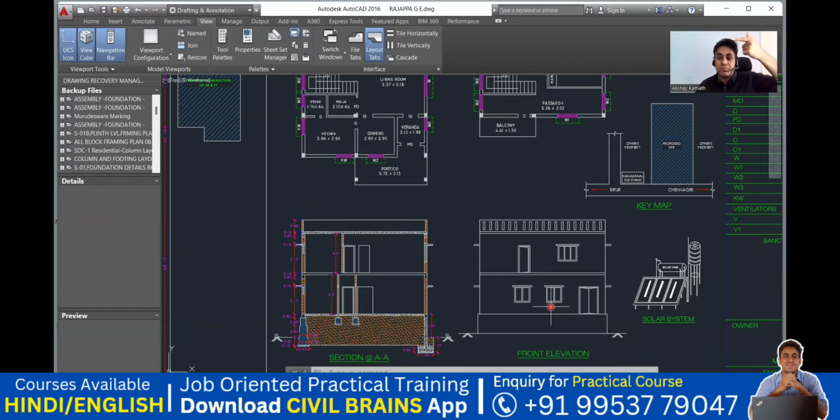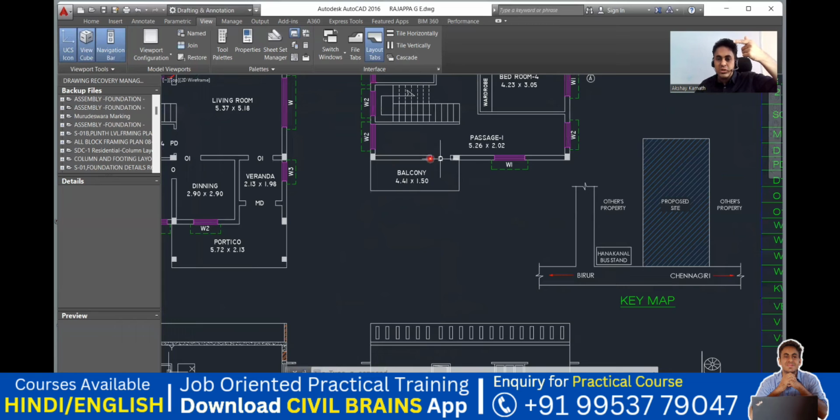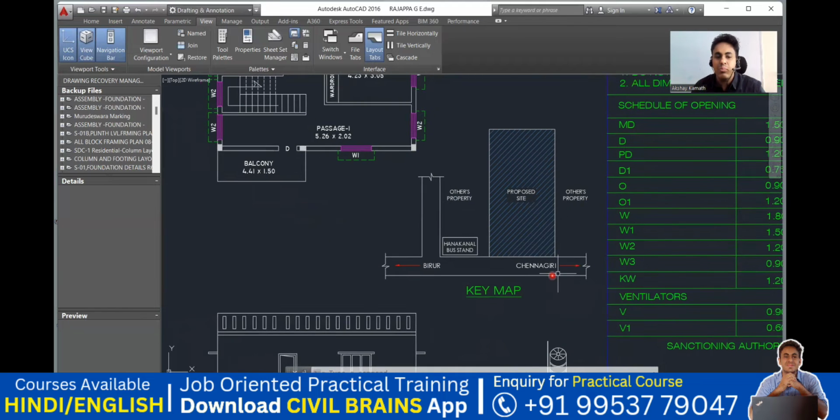I can see the first floor. If you come to the first floor, you can see this door here. You cannot see the balcony in this view, but you can see this door, so that is why they have drawn a door here. You can also see this window. If you go to the top of the first floor, you are going to put a parapet wall, so you can see a parapet wall here. This is how a parapet wall is drawn. Got it?